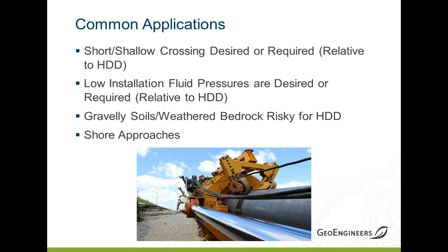We've also designed a number of them in gravelly soils or weathered bedrock, things that you look at from an HDD perspective, and you think of hole stability risk or settlement risk or other things that it looks a little dicey or even unfeasible for HDD. Direct pipe is a pretty good application there. And then we mentioned shore approaches.